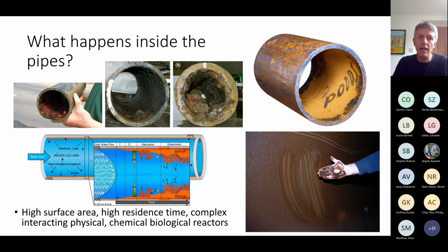You can see, as you'd expect, corrosion deposits inside some of them. This one's more interesting, where you can see really big accumulations of material. Yes, there is some loss, some graphitization of the wall, but this amount of material isn't just corrosion of the cast iron itself. These are accumulations from hundreds of years of very low background levels in the water, and how it can accumulate.